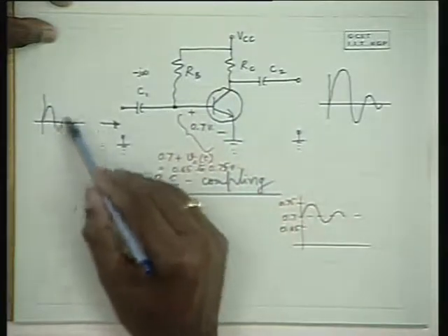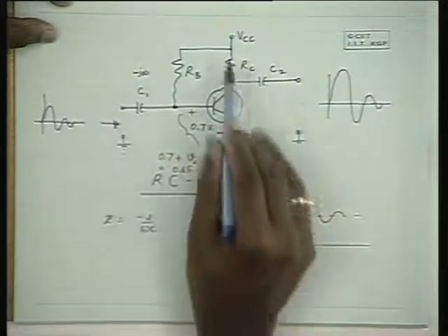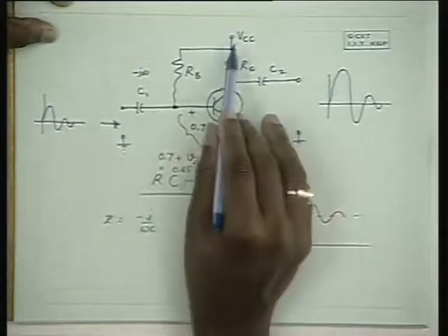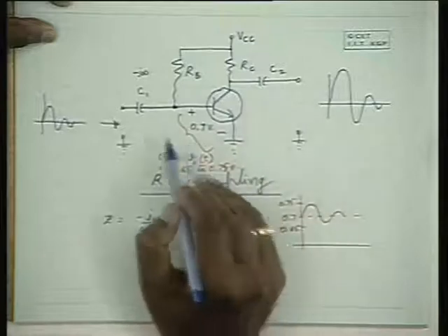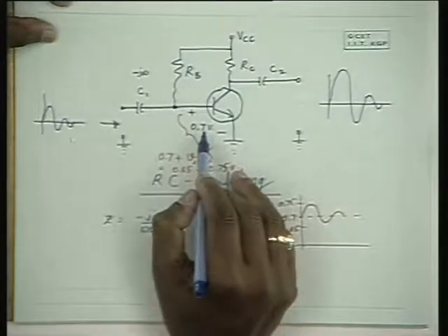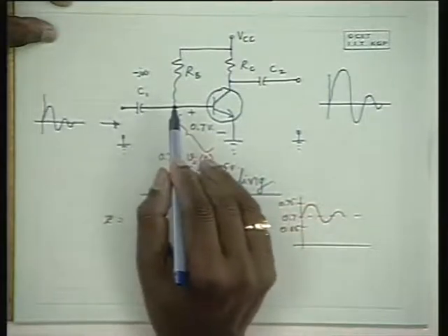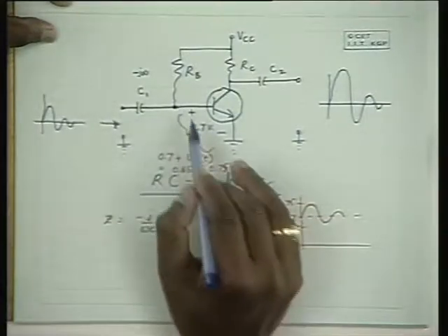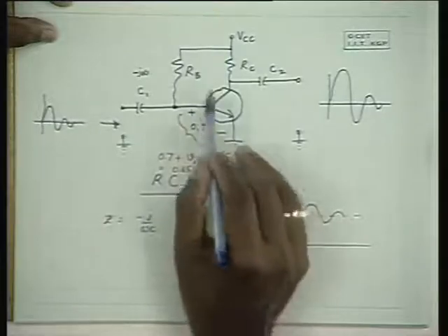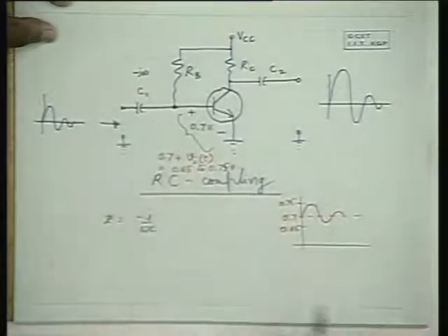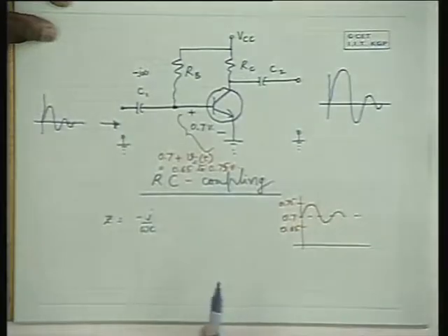Then apply this voltage source, find the component with this source replaced by a short circuit, and see how much is applied. That is directly this voltage itself when this is negligible. Therefore, by the superposition principle, the voltage here is equal to this plus this. So that is what is equal to this.